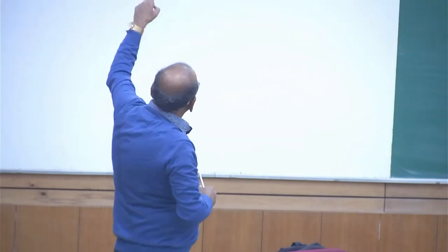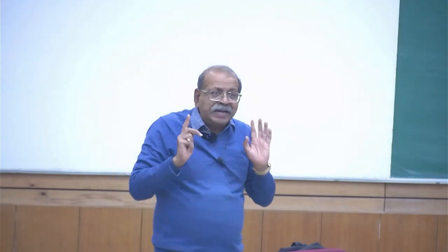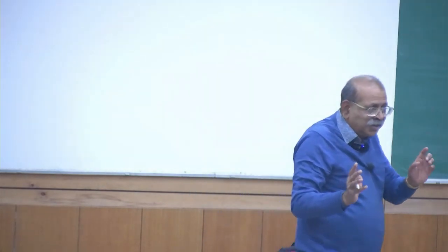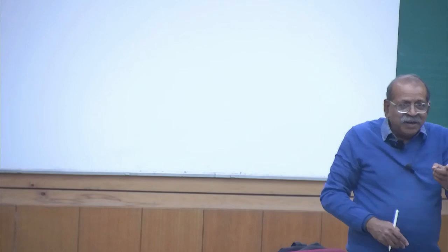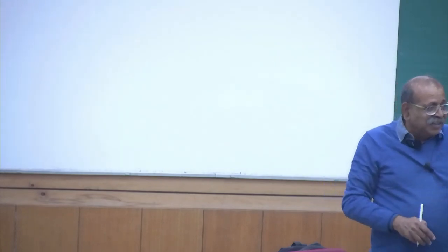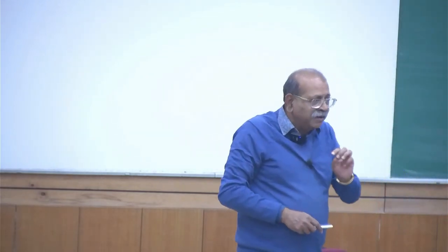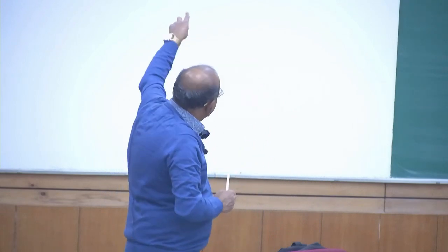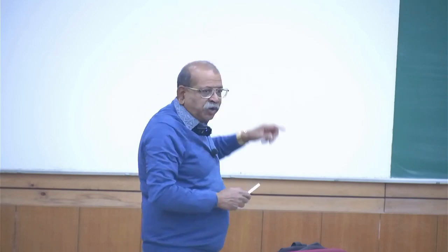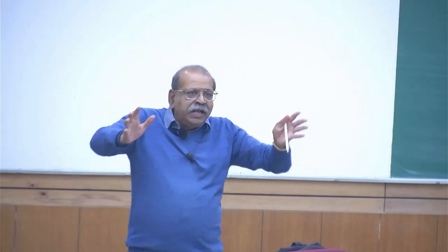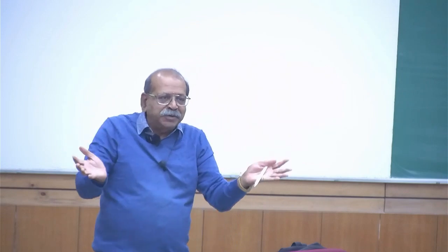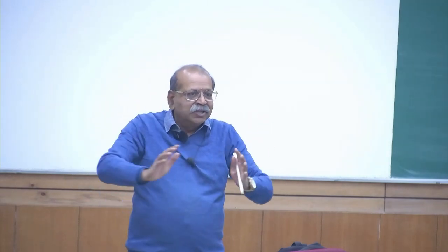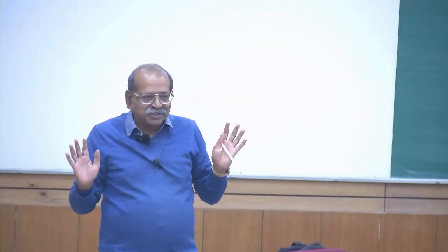Now I have used another word, pure bending. Okay. I am explaining all of these. I explained what is a rod. I explained prismatic. Then I explained bending. Now I am explaining pure bending. Pure bending means the section which we are looking at only has two opposite moments acting. There are no other forces which act.